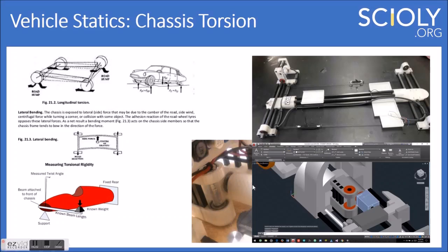I think over here, you can see this free rotation. This was where the caliper was getting attached. You can see in this CAD model, it was free to rotate inside of this part, so that helped with the torsion as well, in that the front could slightly rotate, not just turning the axle angle, but also rotating so that the wheels can maintain different contacts depending on if the angle increased or decreased.